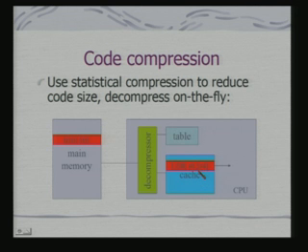The actual instruction can be 32-bit, but my representation can be 8 bits. In fact, I can use any form of entropy coding, a variable length coding, for instruction compression. A very common example of this, if you remember, we had discussed use of Java, J2ME. For J2ME you use an archival format of the code and not the standard format, where the binary code is actually compressed, so that it can be loaded onto a small memory in the embedded system.